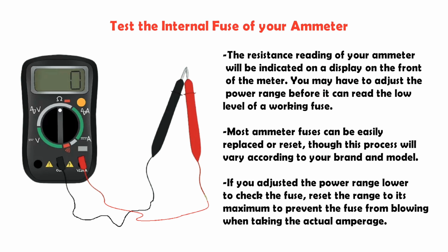If you adjusted the power range lower to check the fuse, reset the range to its maximum to prevent the fuse from blowing when taking the actual amperage.